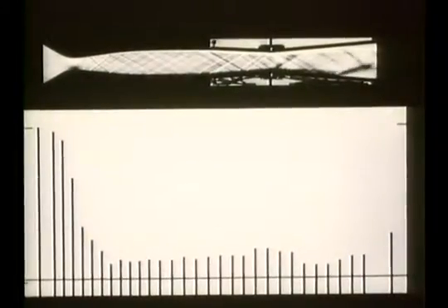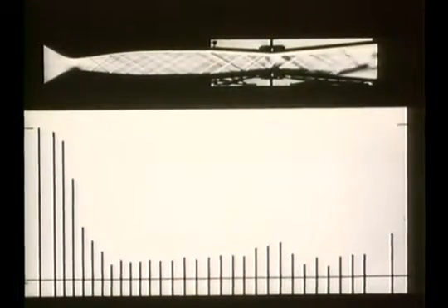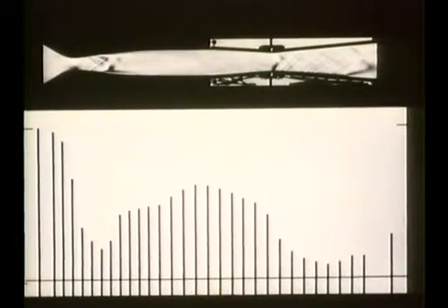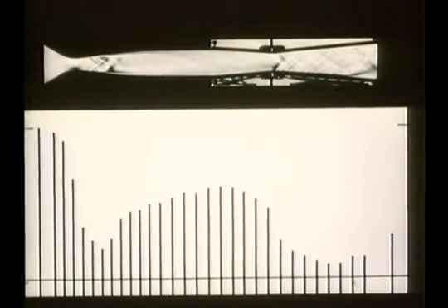As we vary the area of the second throat, notice the wave pattern changing in response to the slight motion of the walls. It's possible to calculate from the wave angle that the Mach number in the test section is about 2.1, while the lowest Mach number we can get at the second throat is about 1.4. This time, watch the manometer as the second throat is closed to block the channel. Note the similar pressure distributions at the two throats.